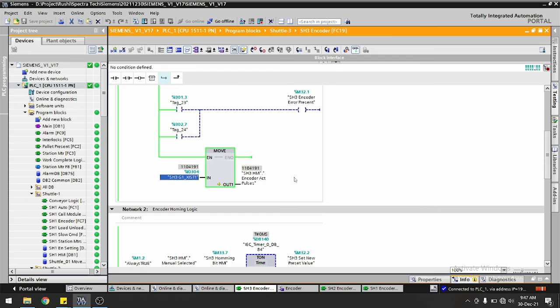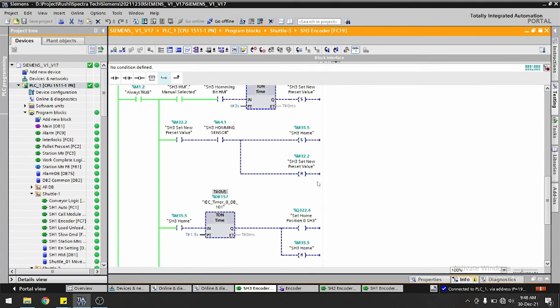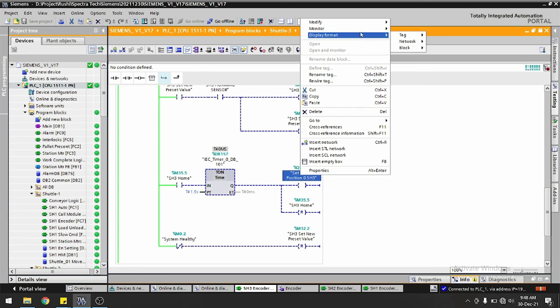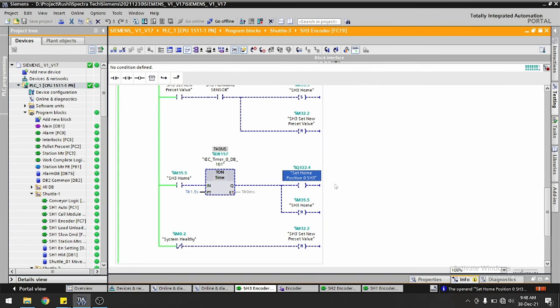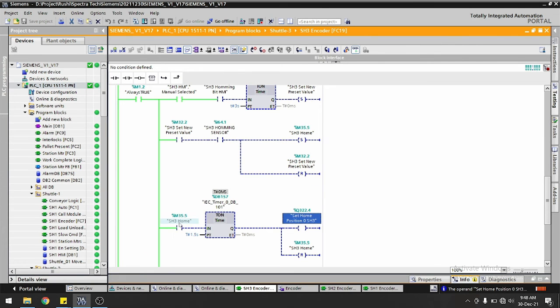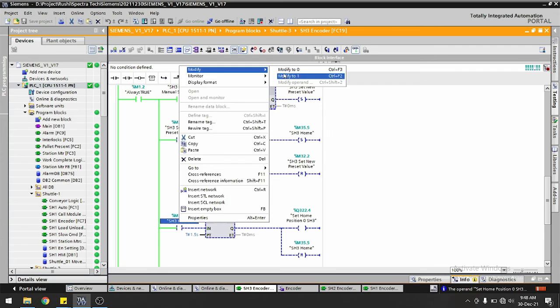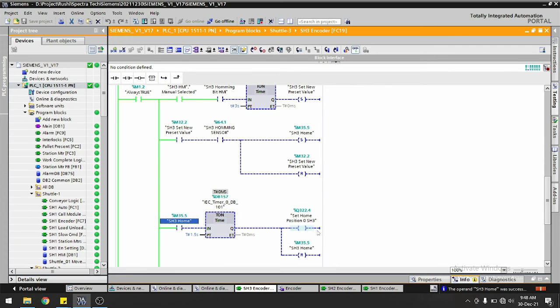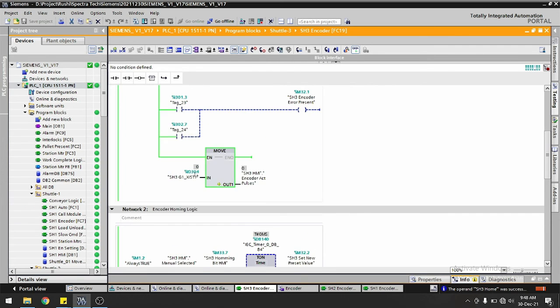Okay, we have just moved it as it is into one register. Now you can see here, if I turn on this bit, the value will be 0, because in preset we have set 0. In device configuration, in the preset bit we have now just clicked on 1, modify 1. Yes, now you can see the incoming value is 0. It means we have homed the encoder. Now if I turn the encoder clockwise, the value will increase. If I turn the encoder anti-clockwise, the value will decrease.